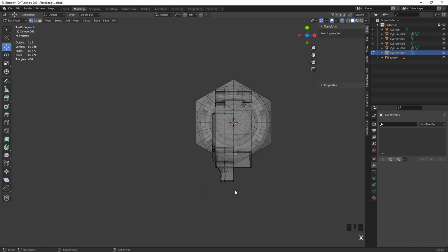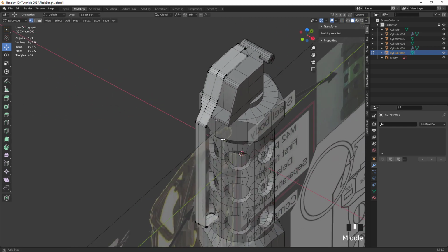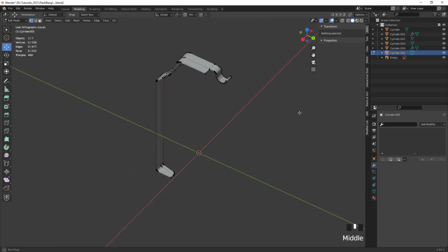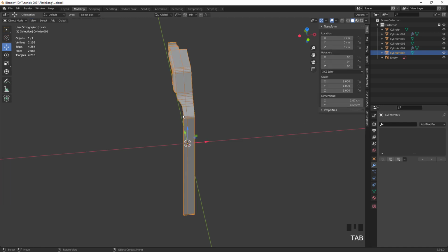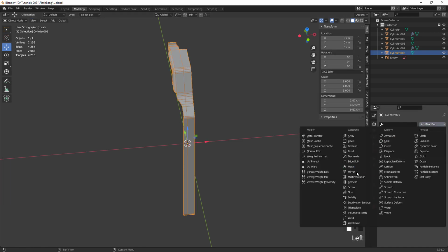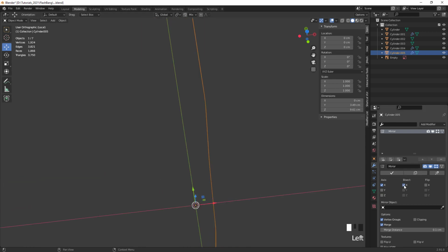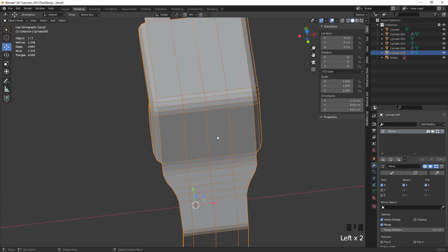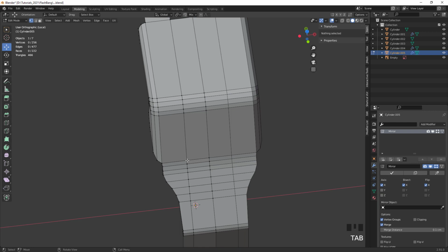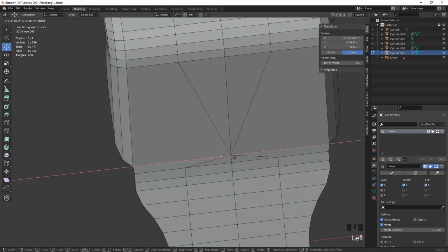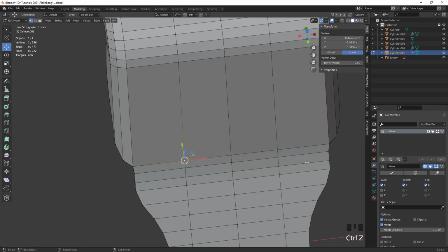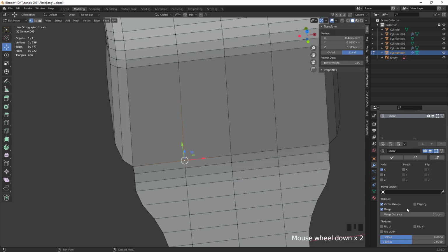I'm just gonna delete the right side of it so that we only work on the left side, and then we can later use the symmetry once again. In that case now, I just want to make sure that we have everything perfectly centered at 0, and that makes sure of it. So now there's one problem here with the snapping. I don't know why that is. I actually opened the bug report for it. Blender Foundation is currently looking into that, which is awesome.